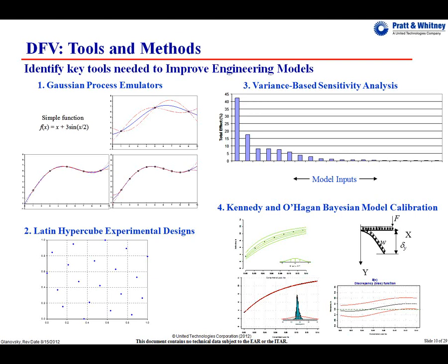Space-filling designs, like a Latin hypercube, are a completely different story, but they've taken to the idea well enough. We explained to them exactly what it is. It's a design of experiment that's meant to use many runs instead of very few, but with computer models, you should be able to afford to do that. You're not spending time creating a lab setup, and then collecting the data from that, so that the emulator built on it doesn't have very far to interpolate between any two possible points.